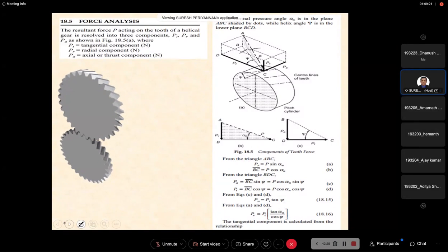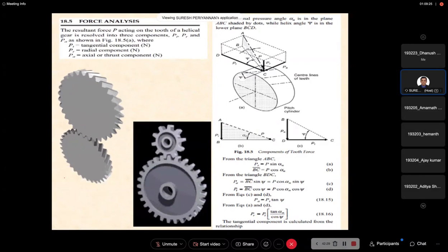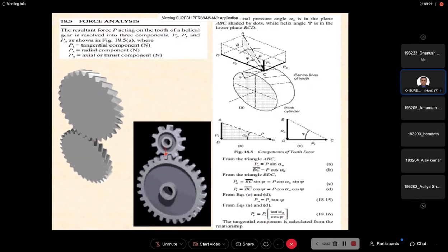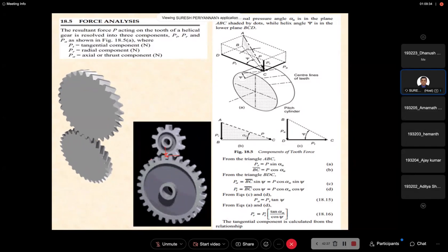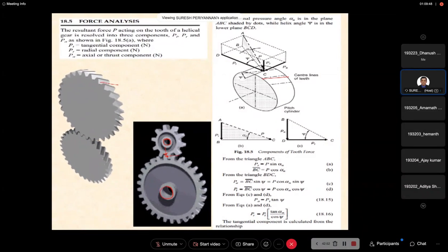Anyway, I would like to show you our spur gear also. Now, in spur gear, what forces are acting? One force is acting like this. The other, tangential force, is acting like this, right? Because the gear teeth and pinion teeth are parallel to the shaft, hence only two forces. Now suppose this is the line, exactly parallel. This is a video.